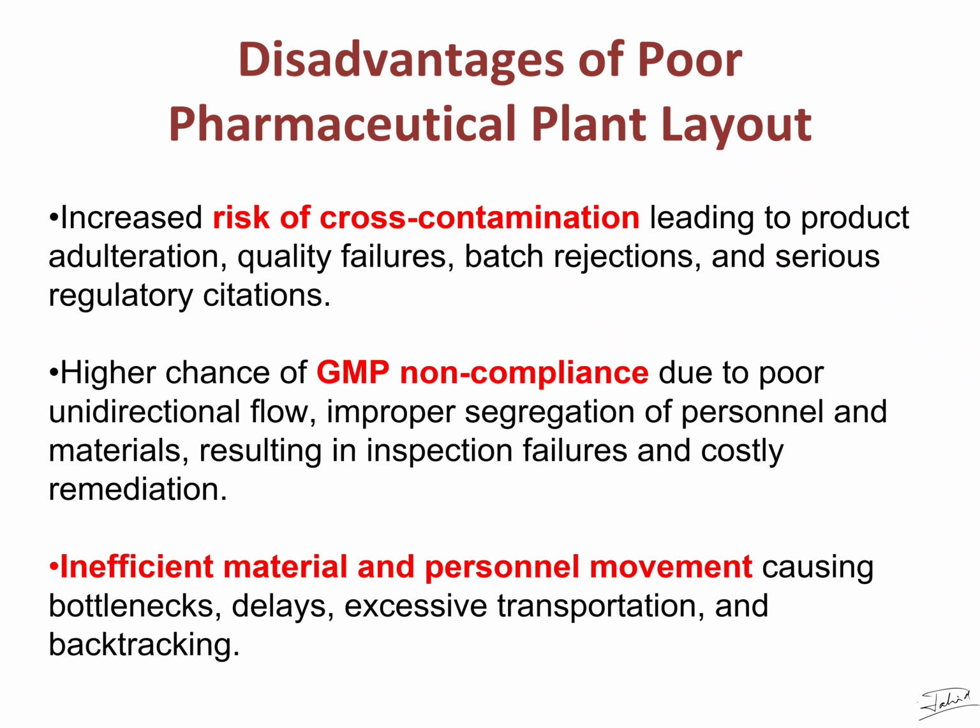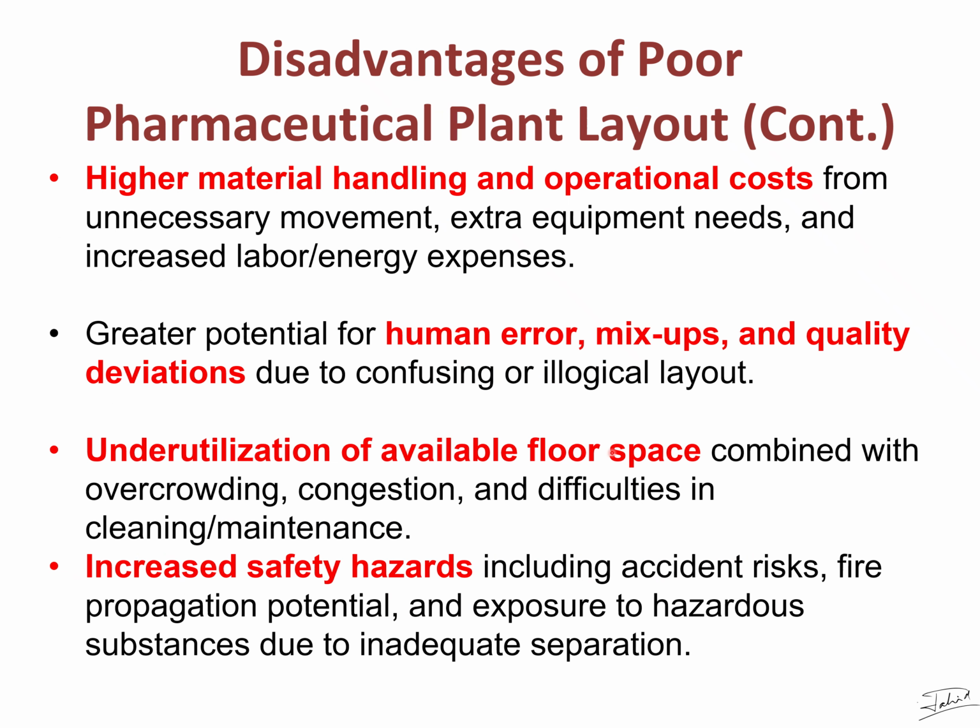However, there are a number of disadvantages of poor layout design, like the risk of contamination. Okay, then GMP non-compliance, then inefficient material and personnel movement. Then due to the poor layout design, high material handling and operation cost. There is a risk of human error, mix-up and quality deviations. There is underutilization of available floor space. Then increased safety hazards. So these are the overall disadvantages associated with poor plant layout design.